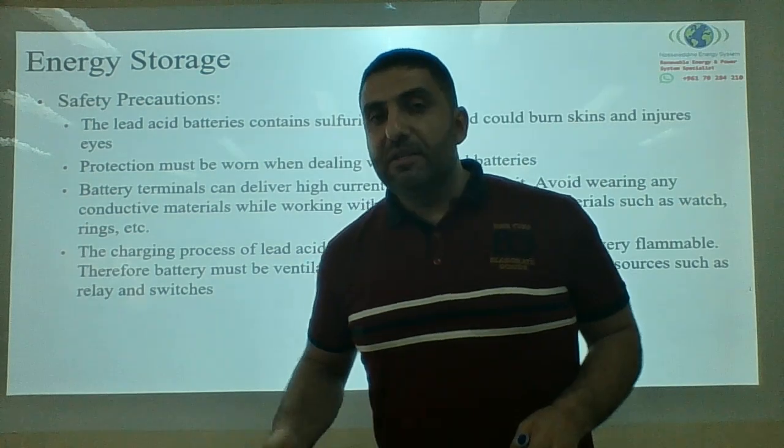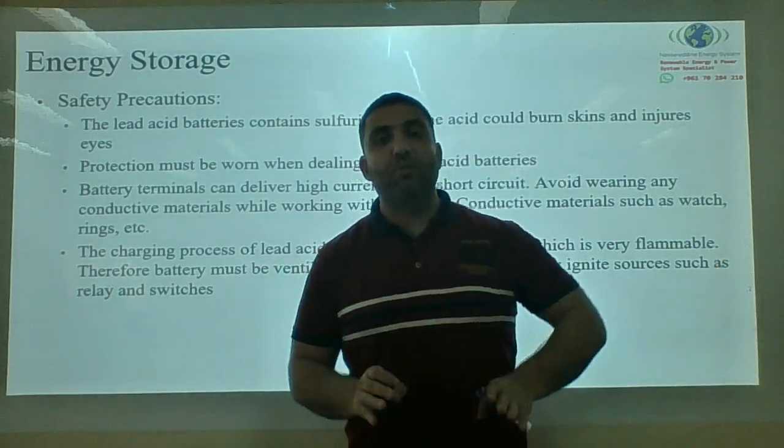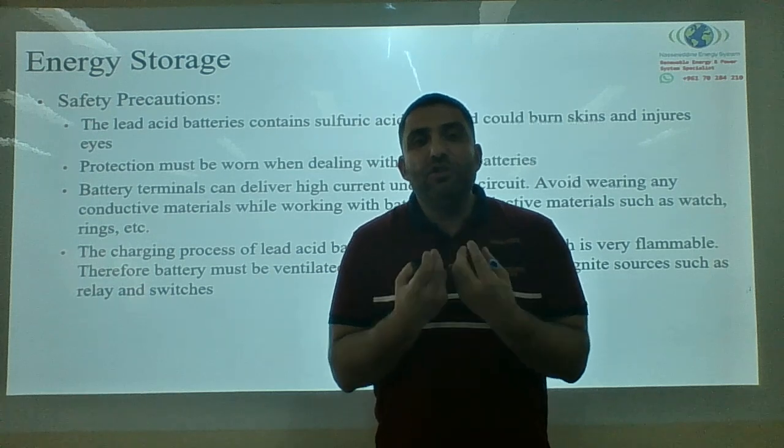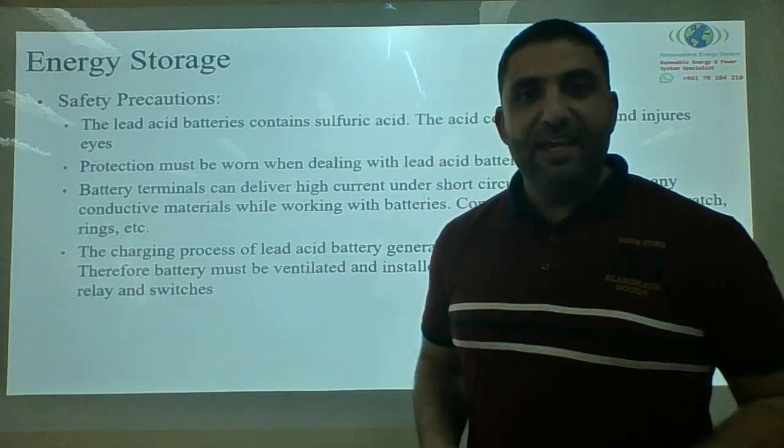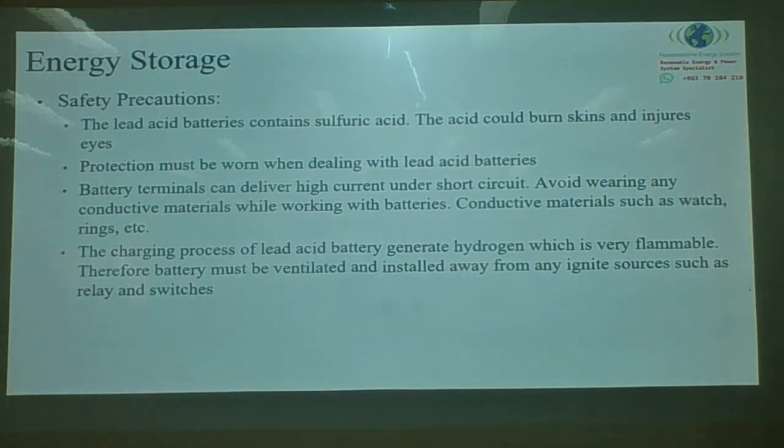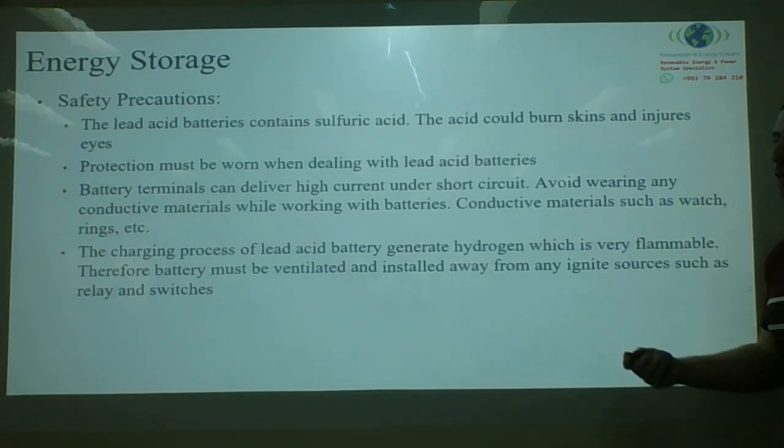Very flammable. That's why the battery must be put somewhere ventilated. You have to use an adequate ventilation system. If you don't use the ventilation system, you could cause major health risk issues, fire, and more damage.